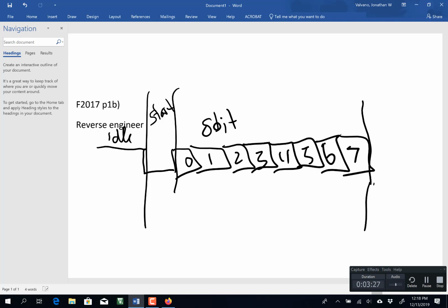And then the next phase is what? One more phase. Use your words. And is it high or low? It's always high. And what comes after the stop bit, by the way? Well, 2 things can come after the stop bit. Another start bit could happen right there, or an idle. So this is either an idle or a start bit.